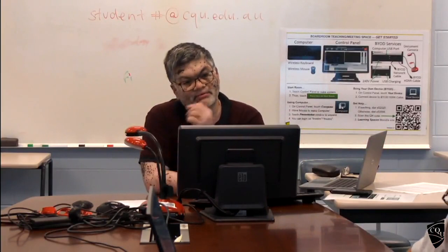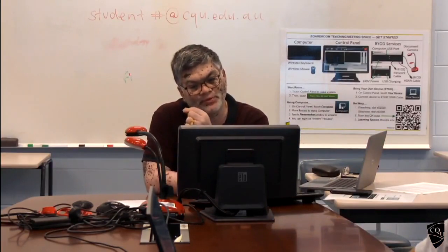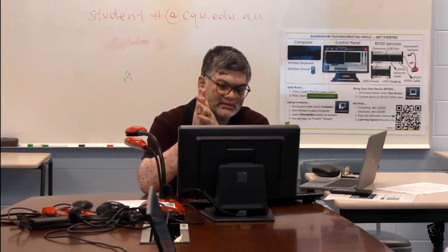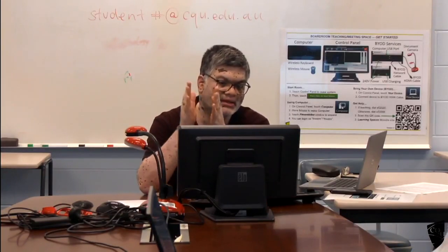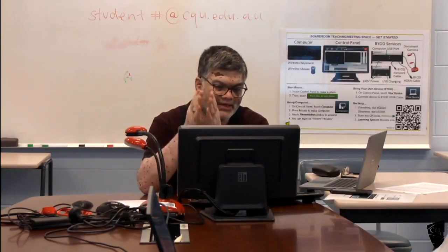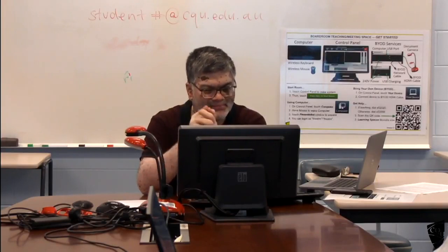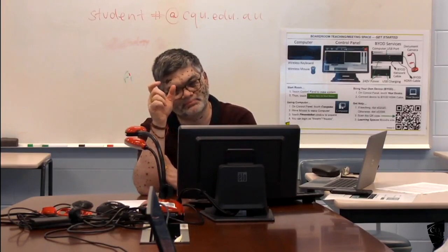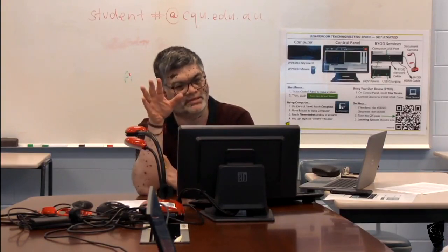Because what we did for one-way slab and two-way slab, we use a 1 meter strip. Remember, that is a main difference. In one-way or two-way slab, we take a 1 meter strip to do the calculations.